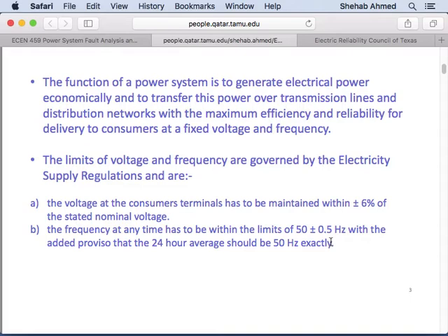What else is important in a generator? The frequency and the value of the voltage, right? How do you control the value of the voltage that's coming out? How was this voltage generated? It was generated by the stator rotating in a fixed magnetic field, or the stator was stationary and the magnetic field was rotating, right? But if this magnetic field is fixed, the E that's generated is fixed.